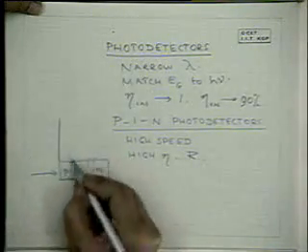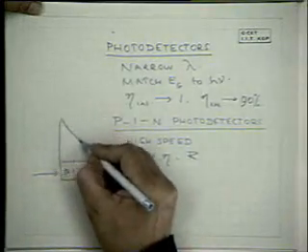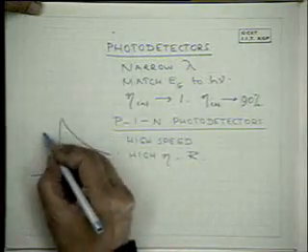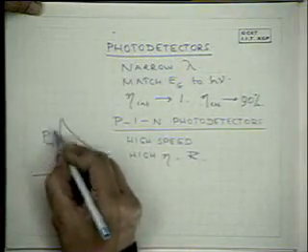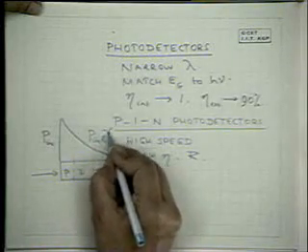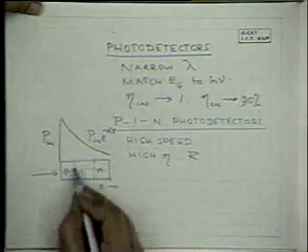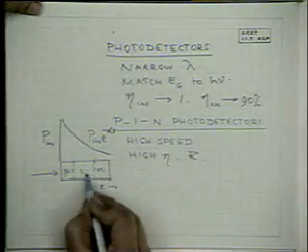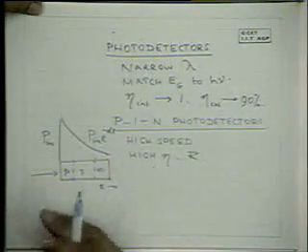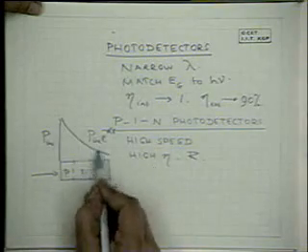then obviously the light is going to be absorbed in the semiconductor as, suppose you have P incident intensity, this is P incident e to the power minus alpha x. So one can adjust this I region width, which can be a few microns, in order to absorb most of the light.